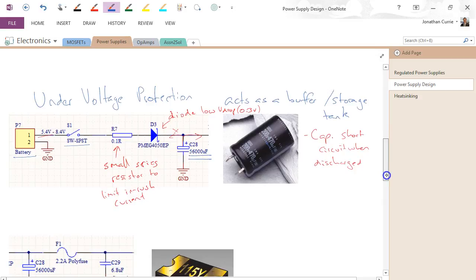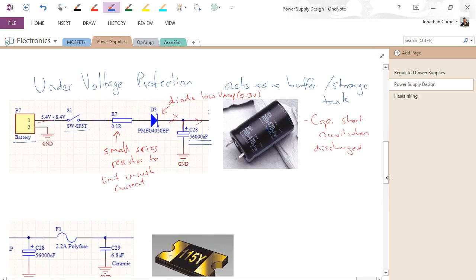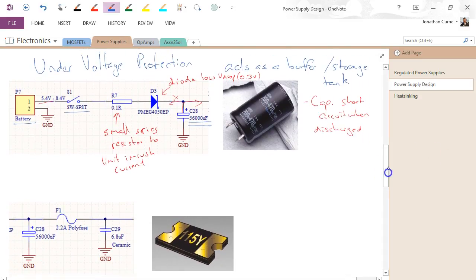It's not always required, in fact it's very seldom required, but in this particular instance, being battery powered with something that could stall with a motor, it was actually quite useful. This is a much more common one. Overcurrent protection. The easiest way to do that is a fuse.